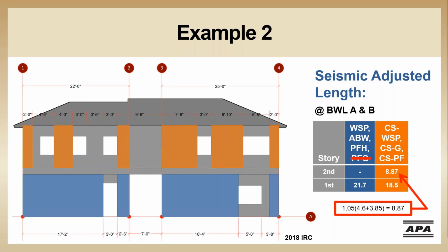Again, you could reduce these panel lengths, but since we're continuously sheathing, we're going to end up with about the same cost from a material standpoint. The lower story might be a little bit more worthwhile of an exercise. So if we reduce that, that would look like this and saves us about 9.5 feet of panel length.